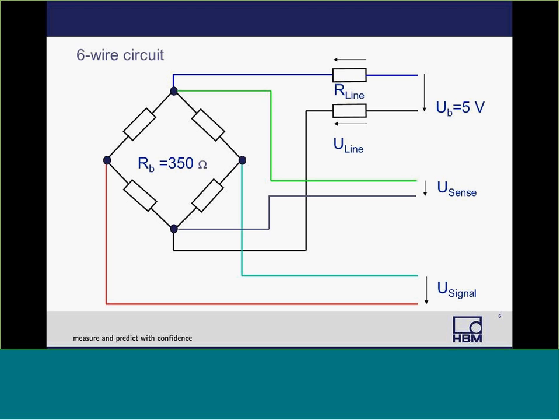But these sensors here that make up the extra 2 wires, what they do is they measure the excitation voltage at the bridge such that a compensating circuit in the amplifier can adjust it so that any lead wire resistances have been accounted for, and that you have the actual excitation voltage at the bridge you desire.